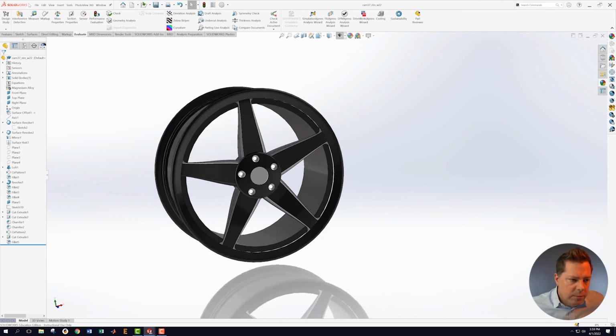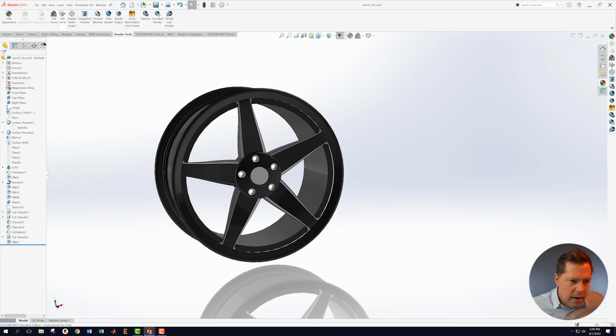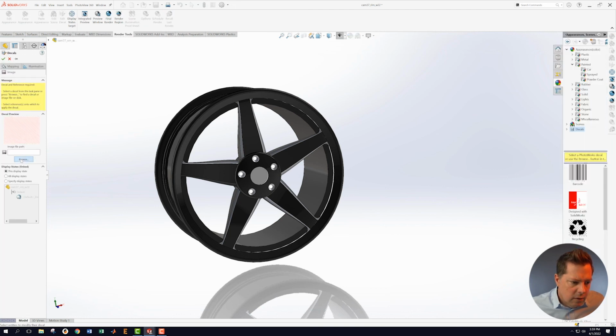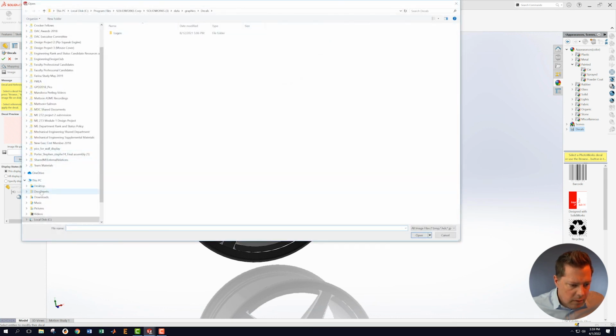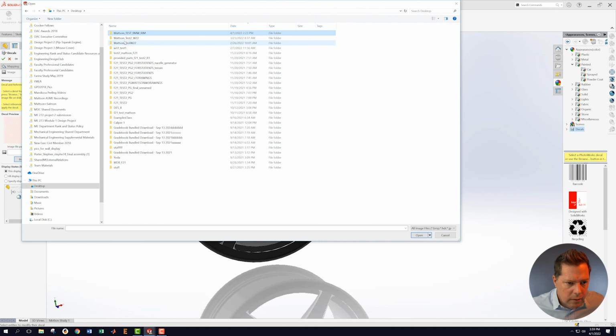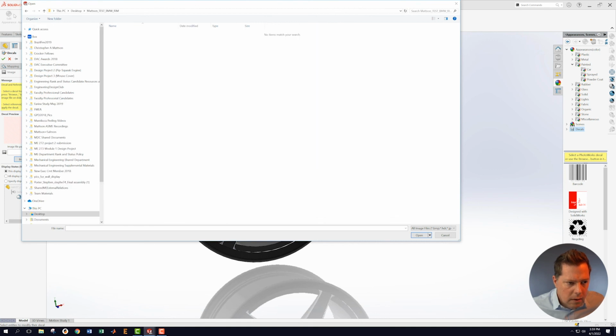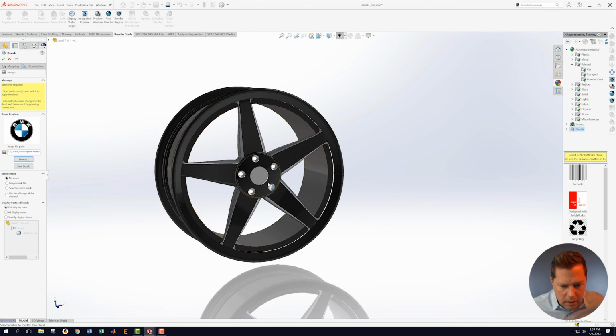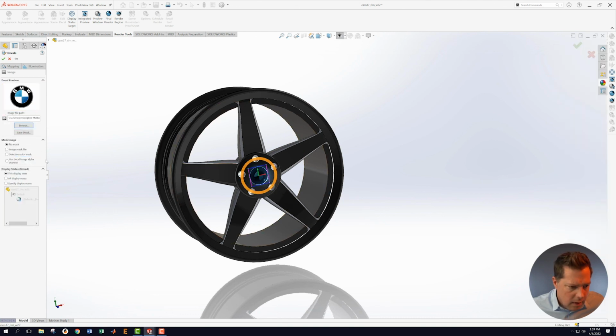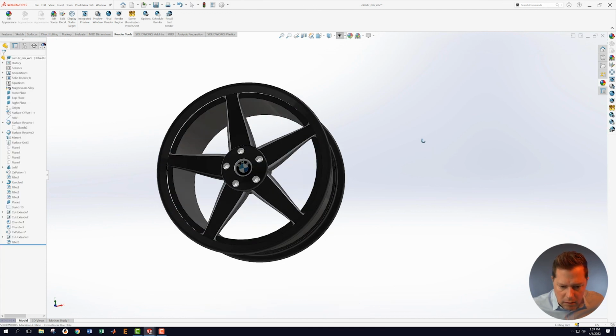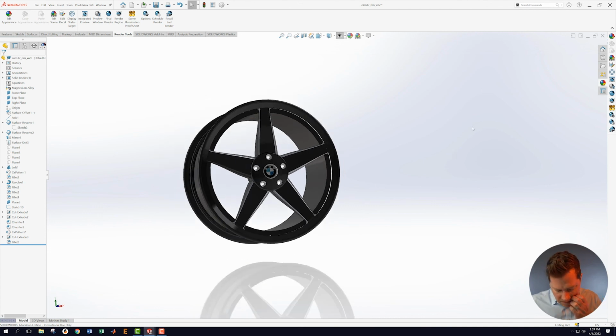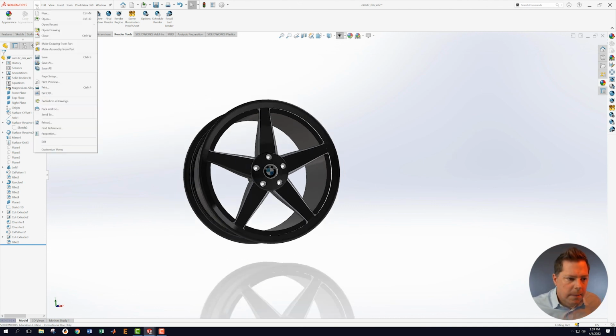Okay, let's look at this in perspective view because I always think that looks a little bit better. Okay, before we put in the decal, actually, let's just stick in the decal. All right, go into render tools. Let's go edit a decal. Let's go find the decal. We want to go into wherever that was. Not there. Here it is. This one. I need to choose a face to have that go on. I want to use the image alpha graphics channel. Just gonna put it like that. I don't need to adjust it at all to make it look right. That's good. Save that.